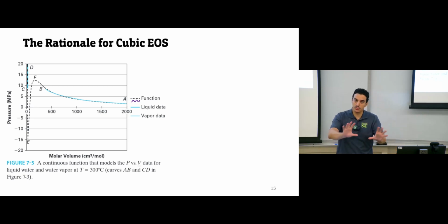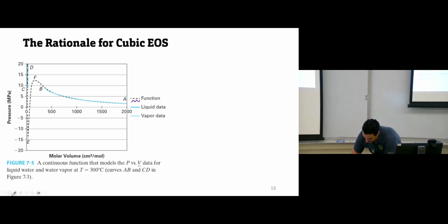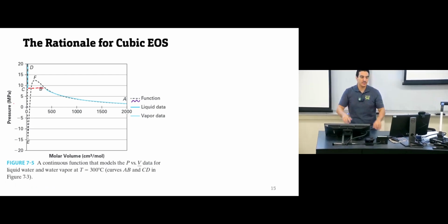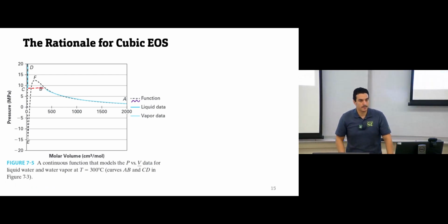Again, for a pure substance, we have certain behavior. There is no math equation that can capture the liquid phase, the mixture, and the vapor phase. But we can have a plot called a cubic mathematical equation. It can capture the liquid phase and the vapor phase, and this is how it looks. The area of the mixture, this one, doesn't lie on this equation, so we are missing just this region. So far is it clear? Okay.